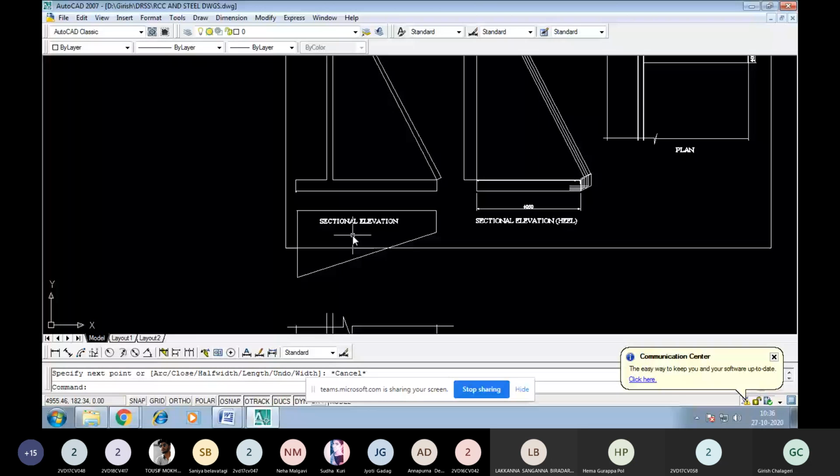Once we get the total H value, from that you design the dimensions of the retaining wall, that is width of base slab, thickness of base slab, width of stem, thickness of stem at the bottom as well as top. Like this, give all the dimensions, length of heel slab, length of toe slab. All these dimensions will be calculated as per the proportions given by the height of the backfill. Then once the proportional dimensions are given for the counterfort retaining wall, check it for stability.